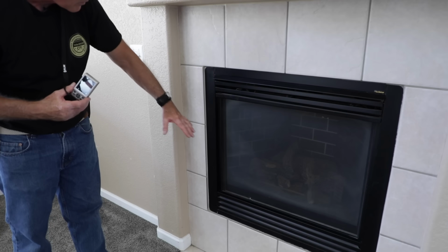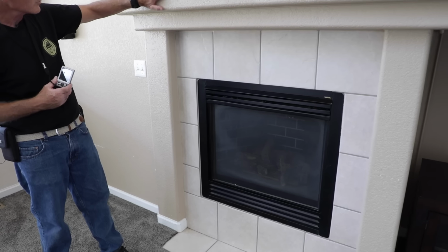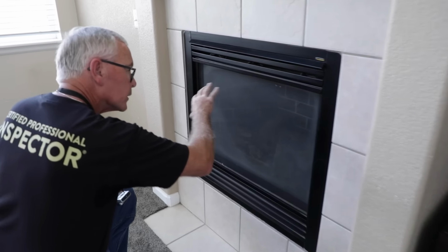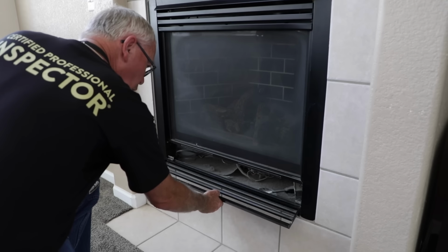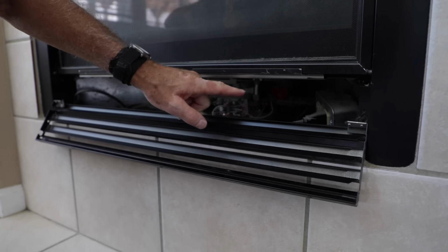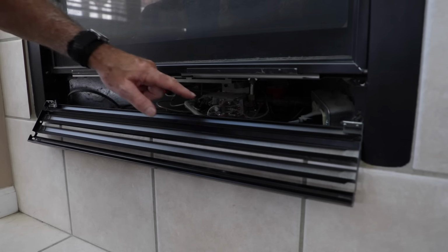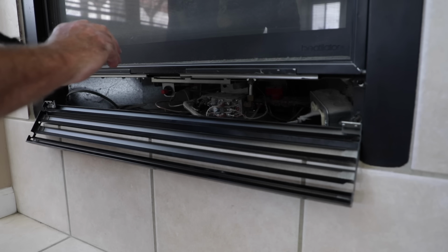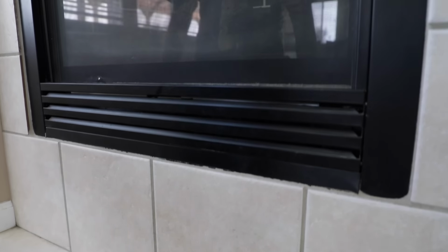Down here at the bottom, I want to make sure that I've got fire-resistant material. This is all wrapped with drywall up here. These doors are sealed or locked into place on these fireplaces. So I'm going to come down here, open up this maintenance panel. What I'm looking for down here, I want to make sure I've got a gas shutoff, and it's in the open position right now. It's pretty dirty down here, so I'll probably recommend a cleaning. Get all this dust out of here. Everything looks pretty good in there, other than all the lint and dirt in there.